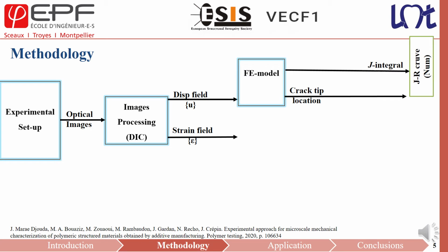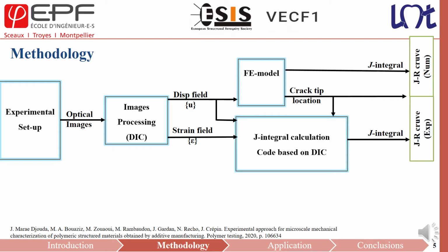From these kinematic fields, 2 ways are explored to calculate the J integral. The first, we use a finite element model. On the second, only measured field is used. First, I will start by presenting the FE model and then the J integral calculation code based on DIC.